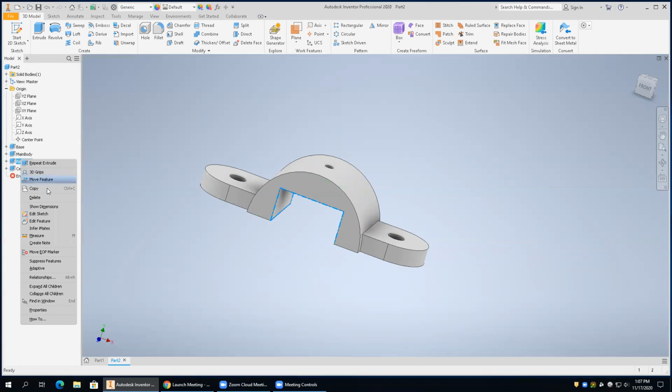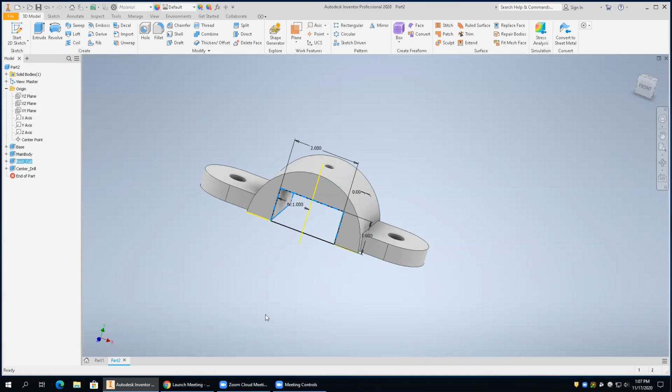And you'll get shortcuts that pop out under rectangular cut. We're going to do what's called show a dimension. I think we looked at this last week. So if we would like to change the height from 1 inch to 0.75, double click your height, change that to 0.75 and accept that dimension.